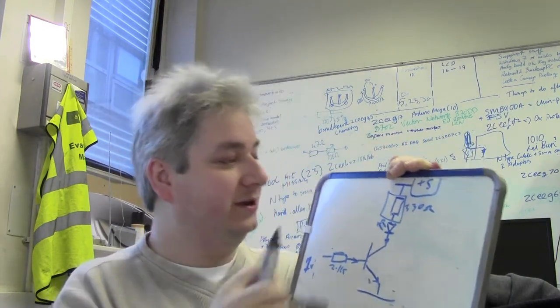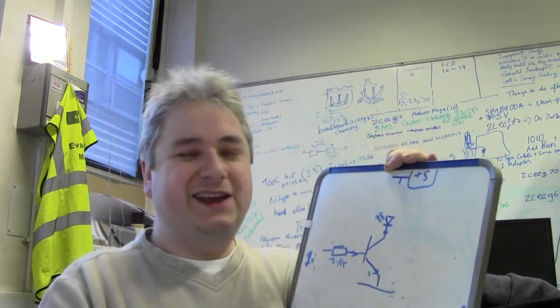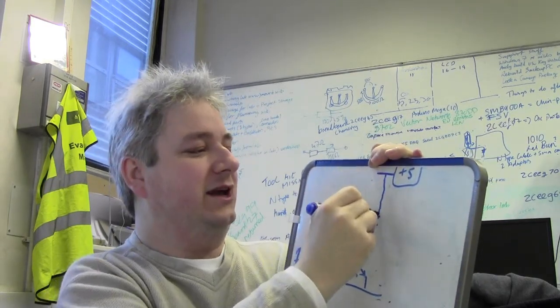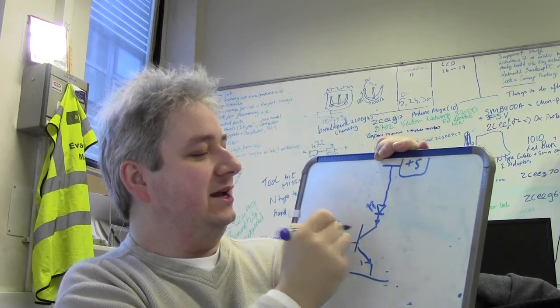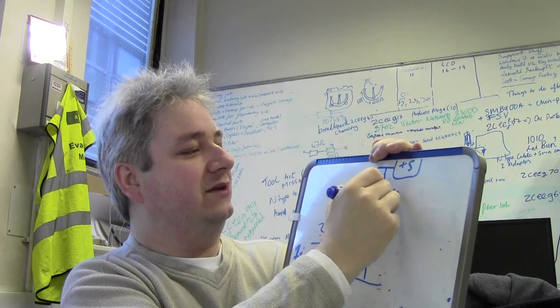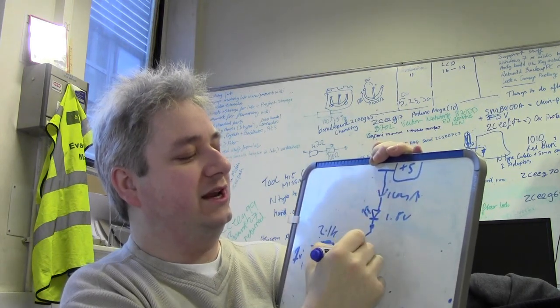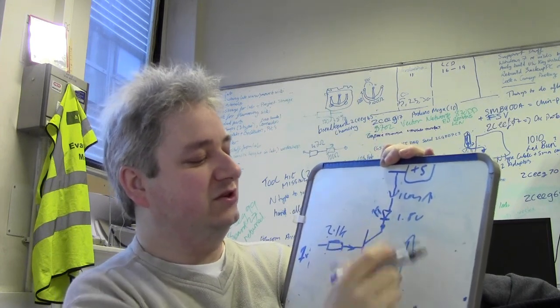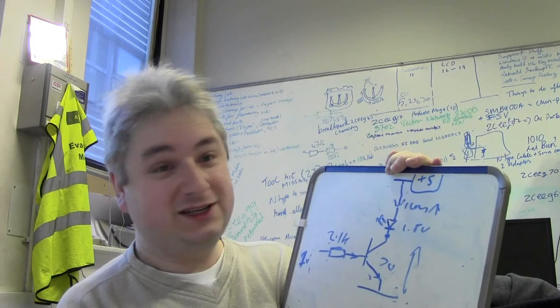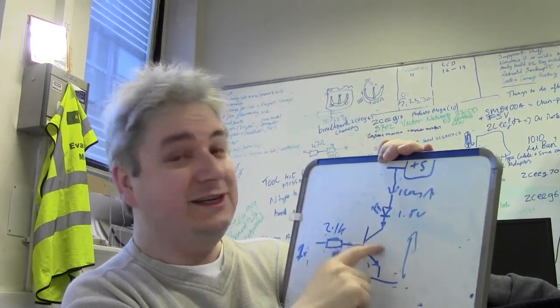Now, some of you might be thinking, and some of you that know all this before say, you don't really need that resistor in there, you can get away with it. If you calculated this out to be 2.1k, you have 10 milliamps flowing down here. If only 10 milliamps flows, you're only going to get 1.8 volts drop across here. All the rest of the voltage is dumped across your transistor. Yeah, you can do it that way. The trouble is this HFE value.